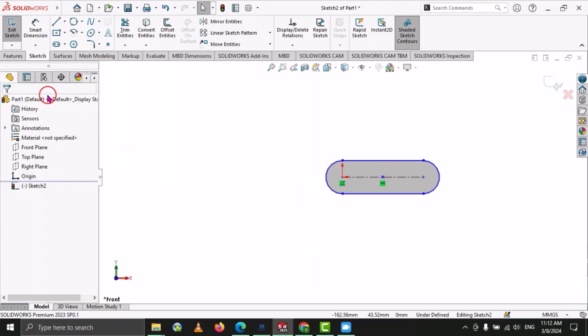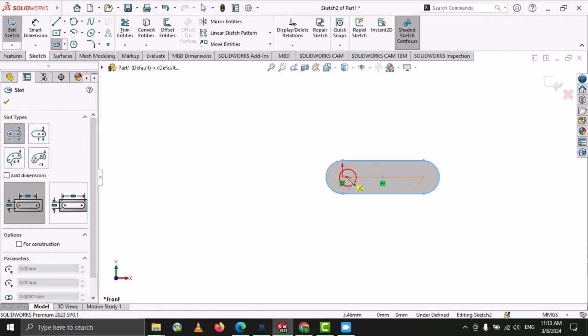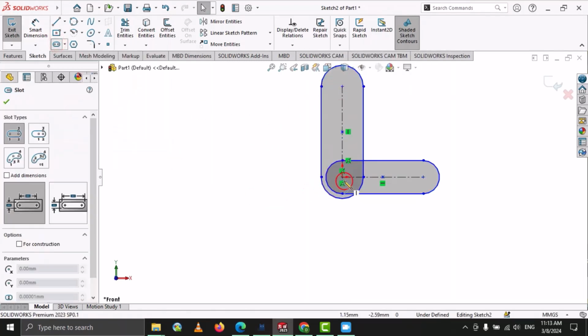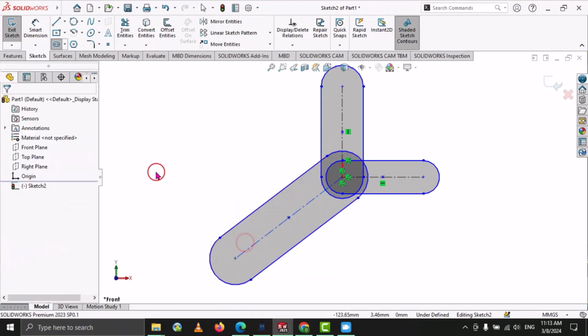so you can see we draw a slot in the right direction. Similarly, you can use this command and you can draw vertical. Select this one, go vertical, select the end point, and then go to draw the slot. Similarly, you can draw at any angle. Okay, let's say select this one, then I go in this way. Okay, this is my end point, and then go to draw the slot. So we can draw a straight slot by clicking 3 points: starting point, end point and the width.